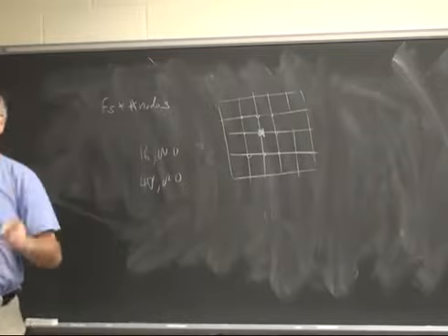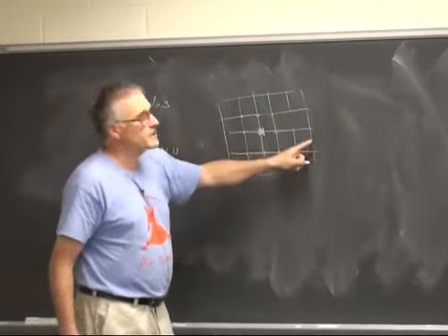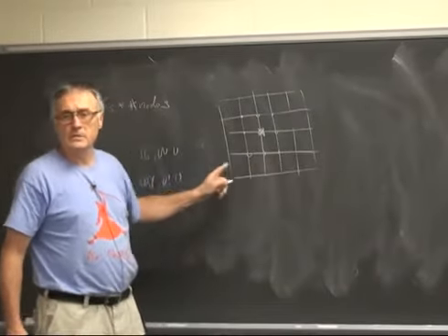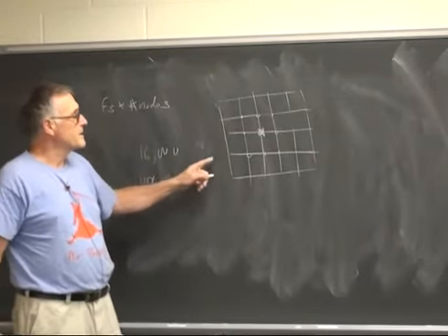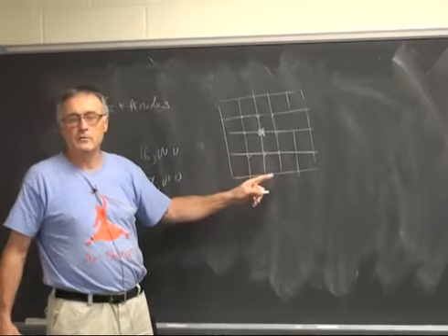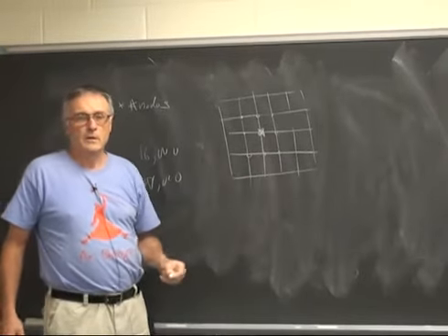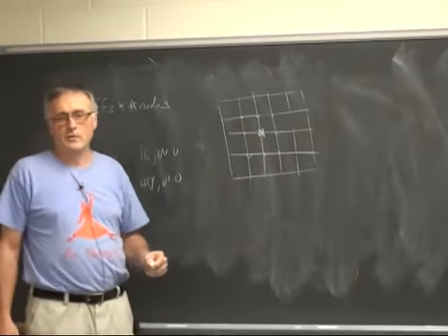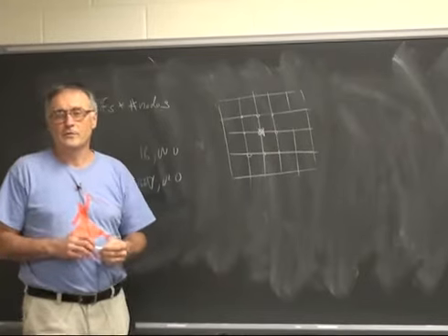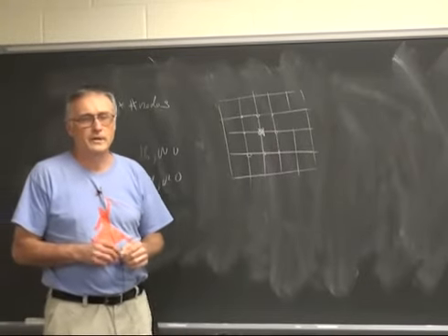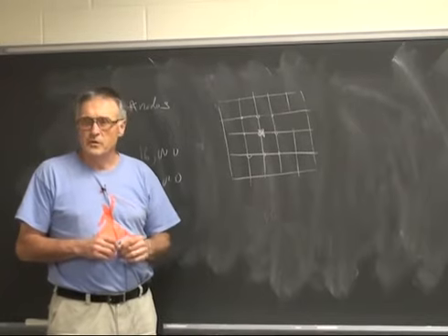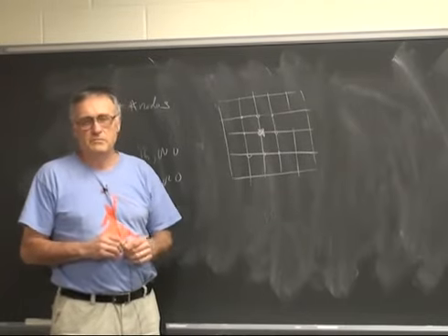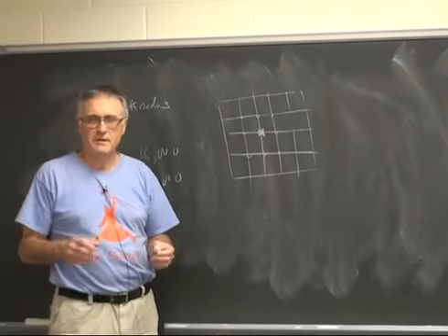So you can trade this off. If you want to do lots of nodes, you can lower the sample rate. If you want to raise the sample rate, you don't have to do as many nodes. I thought I was doing pretty good when I got 100 or 150 nodes running at 48 kilohertz. I figured that was good. A 10 by 10 grid was all right.